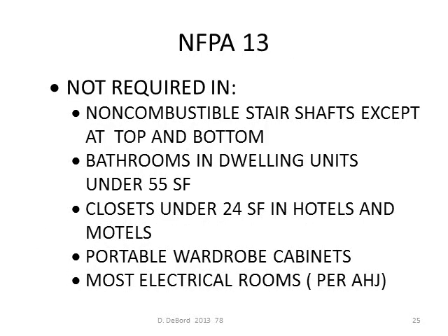Per NFPA 13, it's not required in non-combustible stair shafts except at the top and the bottom. Bathrooms in dwelling units under 55 square feet. Closets under 24 square feet in hotels and motels. Portable wardrobe cabinets. Most electrical rooms, but that's according to the authority having jurisdiction.